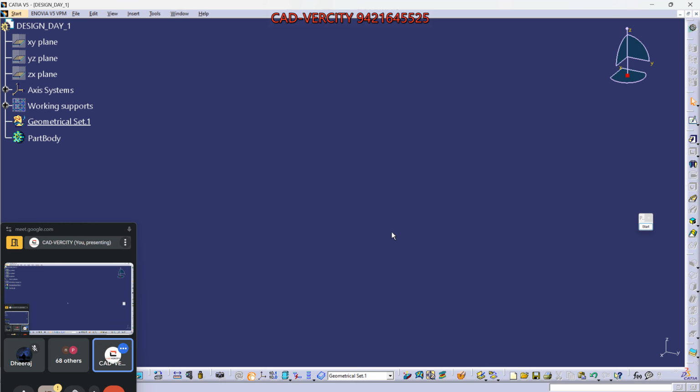Okay. Now tell me, to draw any sketch, we will need some reference. We will need support. If you are drawing, if you are good in sketching, you will need a page and paper, or a pencil. So likewise, I want one plane. In CATIA we use a plane. So how can I get that plane? Pull this tool. Can you see this dash, horizontal dash? Hold it and pull it out like this. Again, hold it, pull it out.